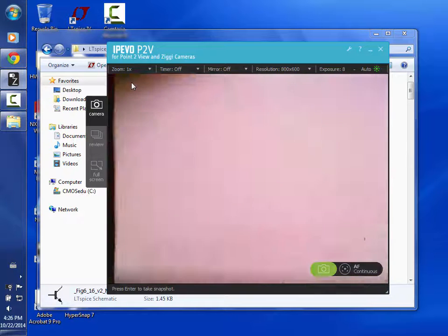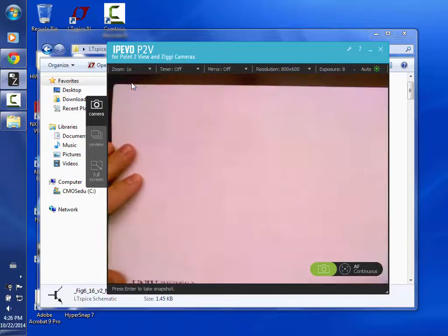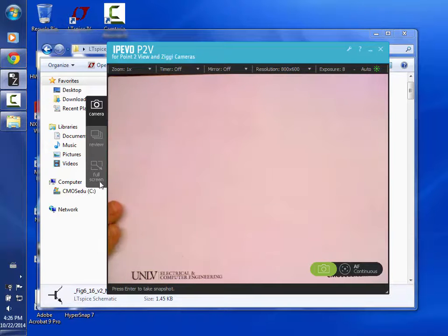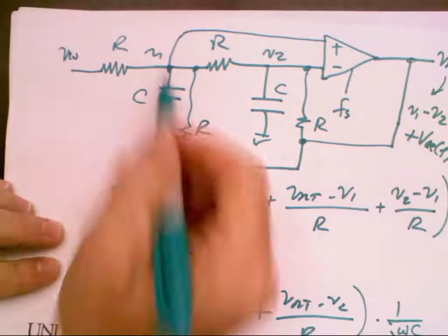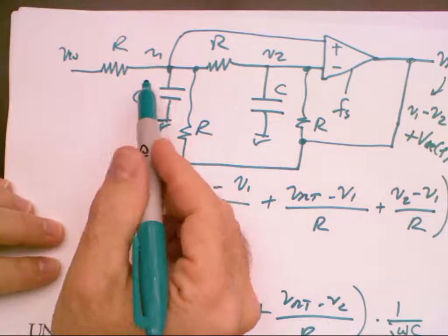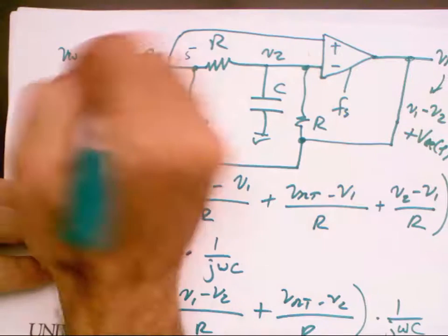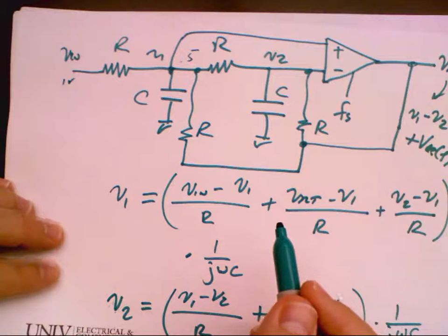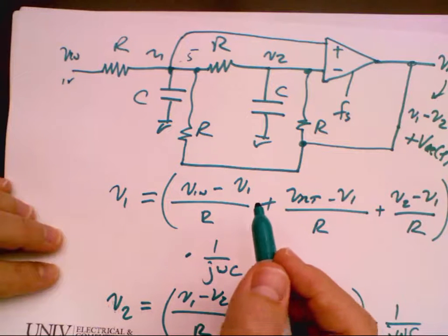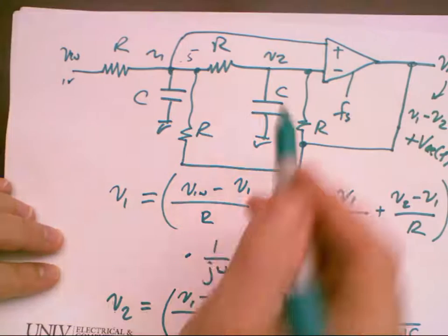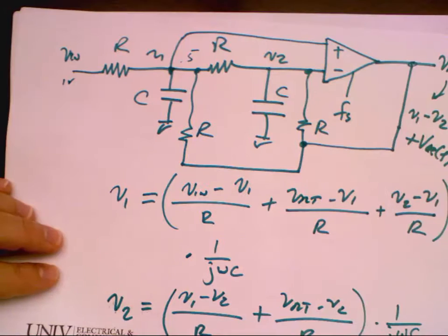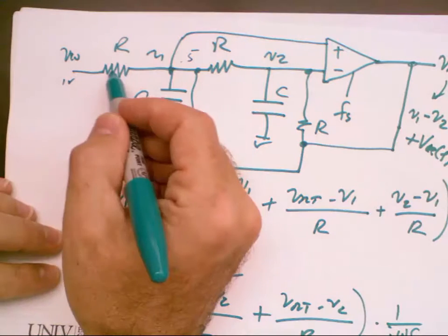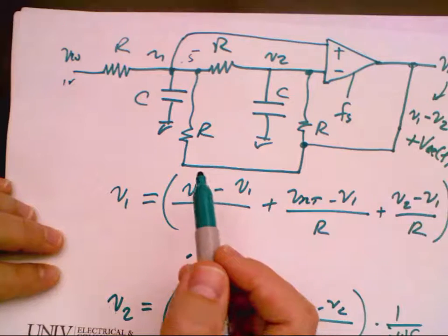Okay, so let's talk about now using switch capacitors, because I just alluded to, or rather said, that when you have an analog modulator, if this was at 0.5 volts and this was at 1 volt, the capacitor would start charging, and so you're burning power. So the next idea is, how can we reduce the power further and not have any static power dissipation? And the answer is to replace these resistors with switch capacitors.